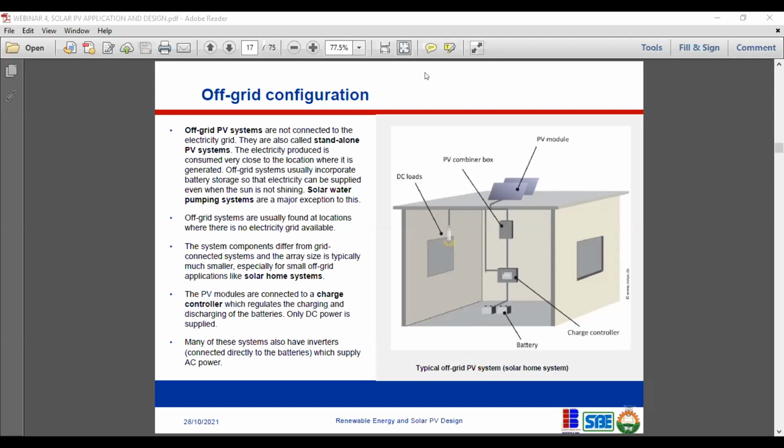Hello? Yes, correct. That's the scenario I have. Okay, so the thing is this: at the time you are doing the design of this system, there's a minimum load requirement for that generator to run, which is in most cases 30%. So you could have, while you are doing the configuration, set that minimum load requirement so that your generator cannot run below that 30% load factor.